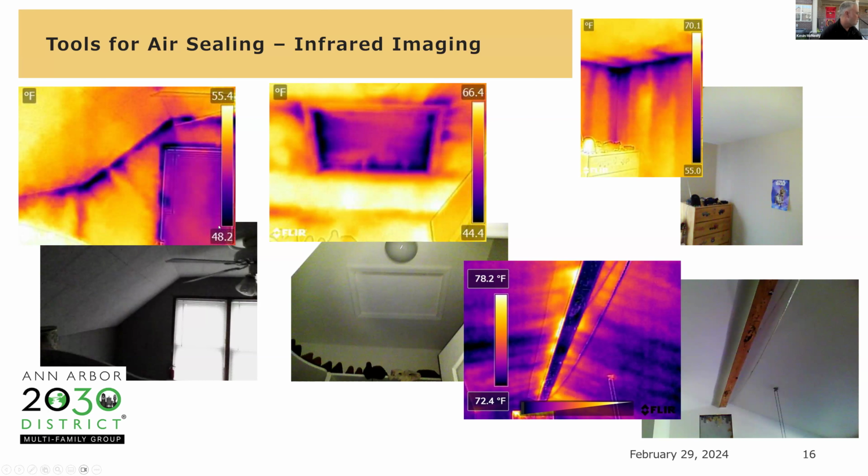Usually if you hire your painter or someone to do that, they don't caulk at the top or the bottom of the window or doors because nobody can see it. So make sure that you tell them to caulk up at the top of the door or window, and also the bottom. And then here's air movement through a wall assembly.